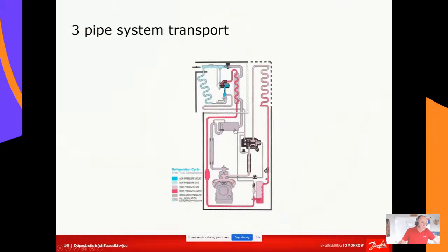And in a defrost mode, we take hot gas up here, down this line. We feed it in to, let's say, the expansion valve. In this case, it's got a side port on it. And then we feed hot gas through the evaporator. So we have a defrost, bring the suction line back, goes through a heat exchanger, goes through a suction accumulator, and then it comes back to the machine.